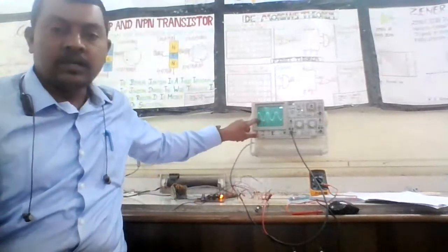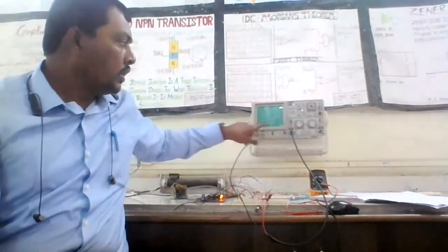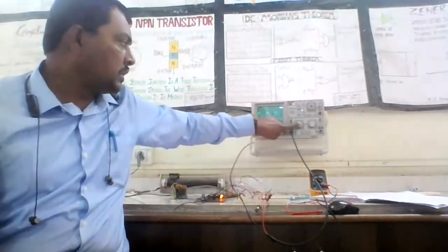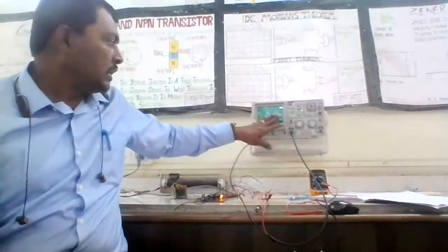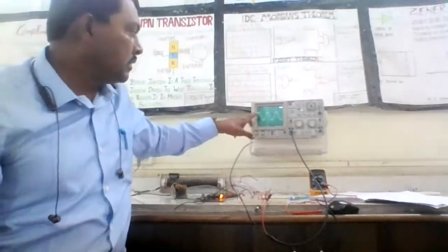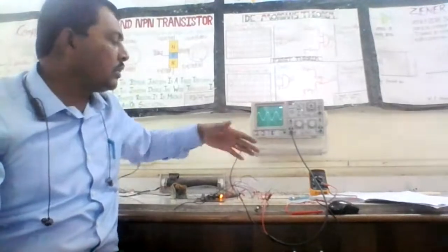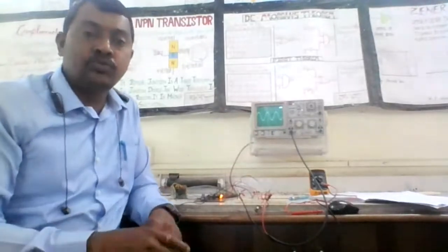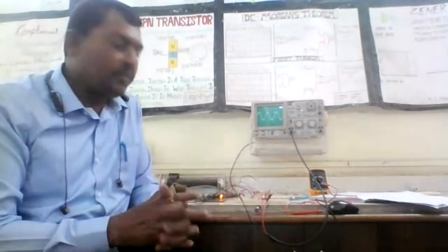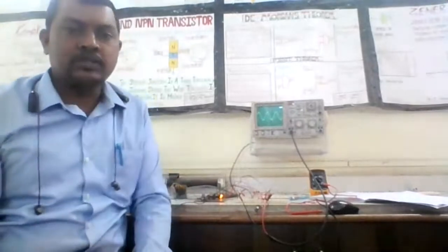These are the AC cycles that we are having. The peak to peak voltage is around 20 volts, right? It is showing a very nice voltage as well as frequency. They are very fine, and they are not damped actually. They are pure sine waves. This oscillator circuit can be used to generate different frequencies by just changing the combinations of RC networks. I guess this much is enough.